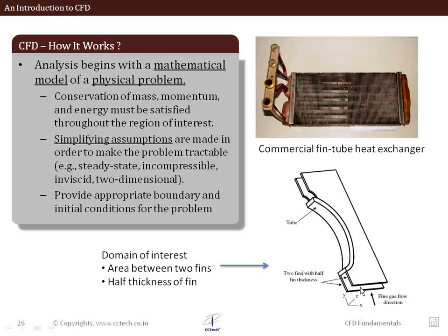Now if very hot air is being passed through this system, as you can see here we have flue gases flowing between the two fins, the temperature variation is quite significant and does vary the density of the fluid, so it has to be taken into account. And we'll be seeing how heat is transferred across these fins into the tube, in which there is cold water flowing. So these are the boundary conditions we need to define to specify the problem entirely.